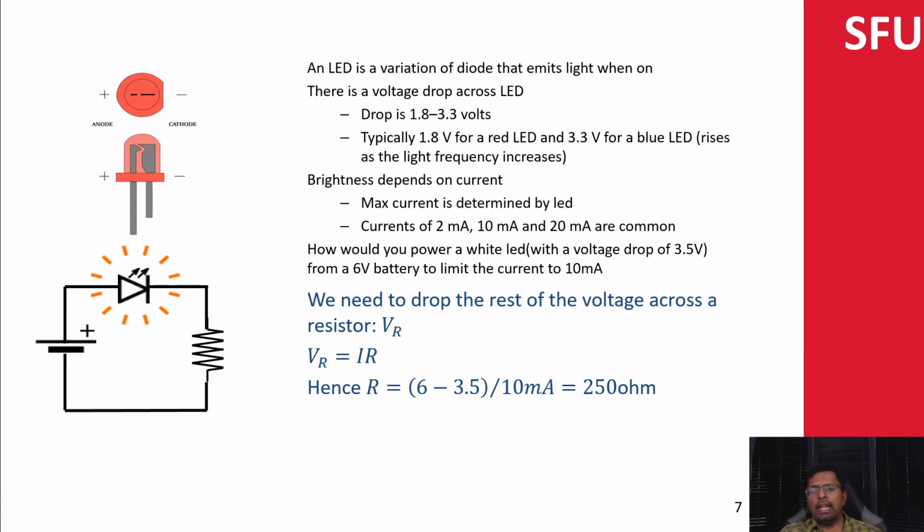This is one of the very simple examples of how you can calculate the diode rating and so on. Instead of this 250 ohms, if you increase it to say 300 ohms, and do the calculation again, you'll notice that the total current flowing through the circuit is going to be smaller. This is one of the examples you can try out and calculate this value.